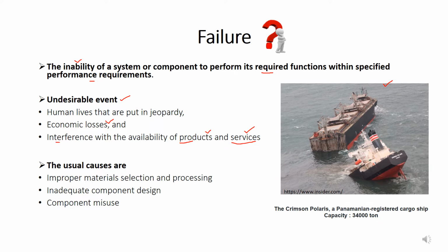And what are the usual causes of the failure? The usual causes are sometimes improper material selection and processing. If the designer of a component is unable to select a good quality material, then that can lead to the failure. And if there is an inadequate component design, meaning if you have designed a specific component and you have not considered the required design criteria, like how much load that component can bear, that can also lead to the failure.